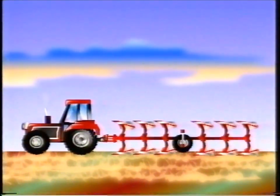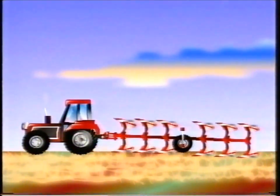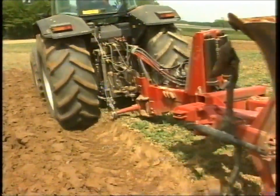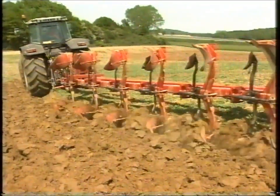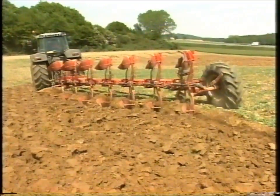Without dual control, there are several disadvantages. Firstly, there's the problem of uneven depth of work and poor finish, because when operated in draft control, only the front of the plough moves in response to changes in draft. This is further complicated when a mid-mounted depth wheel is fitted, because when the front of the plough is lifted, the rear of the plough will dig in.